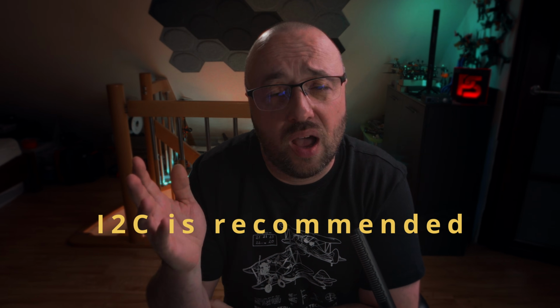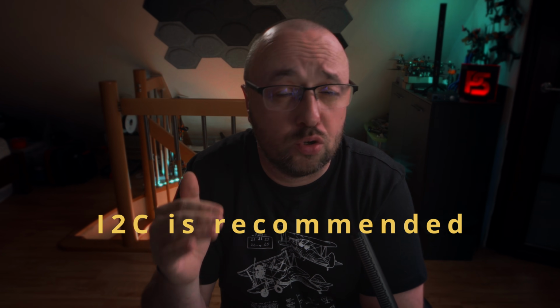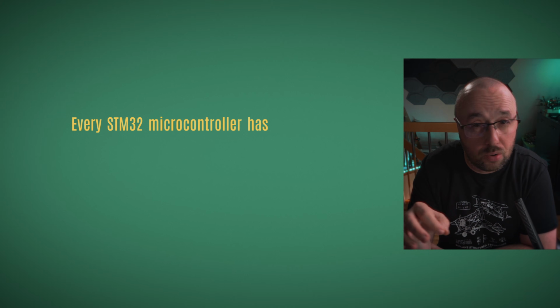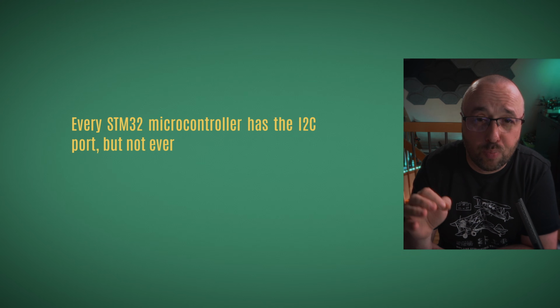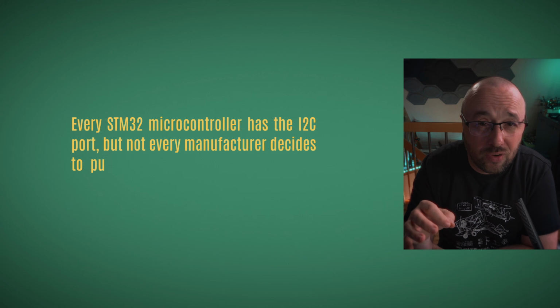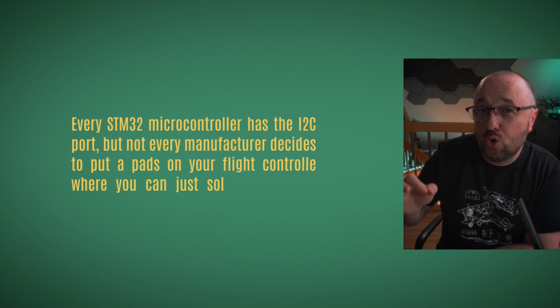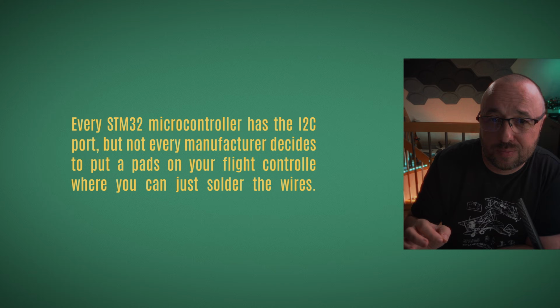I2C pads are advised, not strictly required, but if one day you want to connect, for example, a magnetometer or external barometer, you will need I2C ports broken out. Every STM32 microcontroller has the I2C port, but not every manufacturer decides to put pads on your flight controller, when you can just solder the wires. So pay attention and rather choose a flight controller that has the I2C broken out.